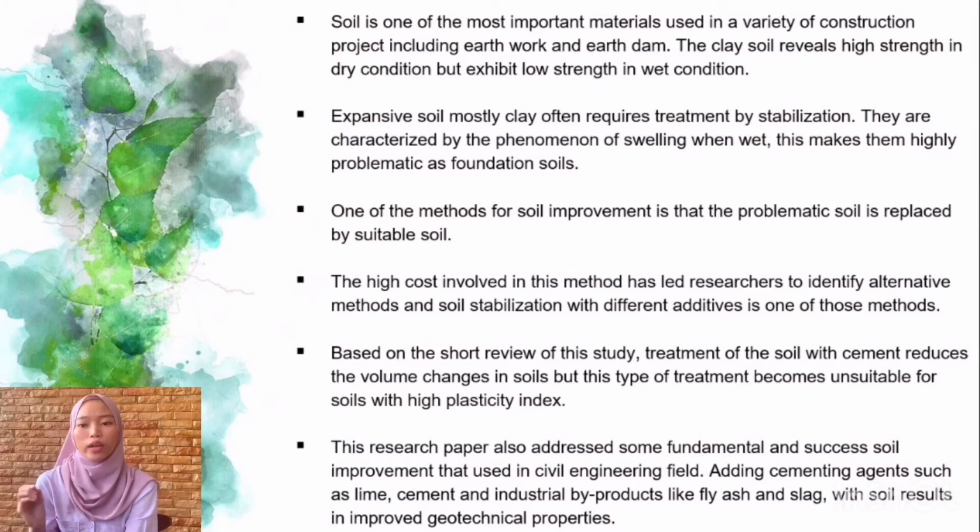Clay soil is widely used in most construction projects as it has good plastic properties, so increased moisture results in decreased shear strength, compressive strength, and volume changes. The soil behavior can be a challenge to designers building infrastructure plants on clay deposits.